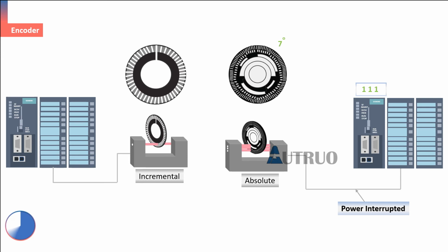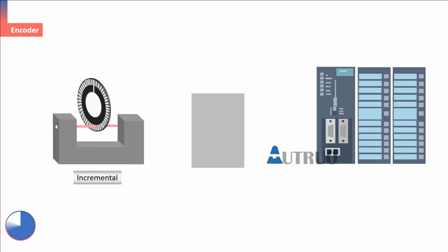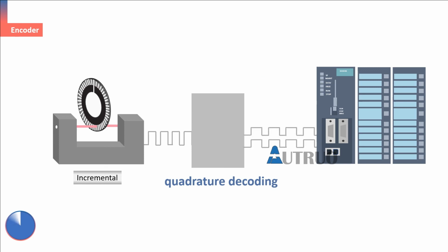Equally important, an absolute encoder will provide a true position in real time, because these days, more systems are becoming digital with connections to a central communication bus, and being able to poll the encoder for real-time position when needed, with minimal latency, is of great benefit. This enables you to keep track of your position in real time. However, with an incremental encoder, even when homing sequences are carried out during startup, you will need to keep track of all the pulses with external circuitry, typically via quadrature decoding. This extra circuitry connection results in some latency in determining the position of the encoder in real time.